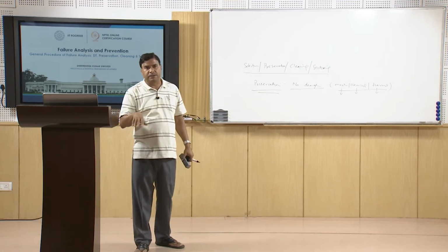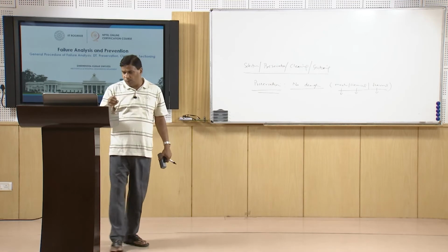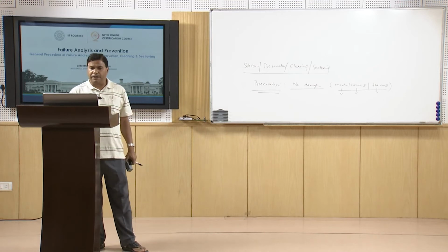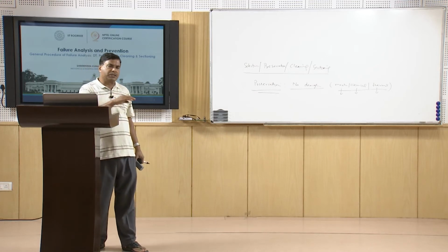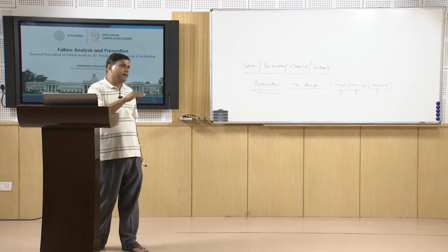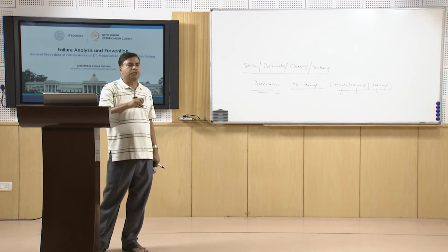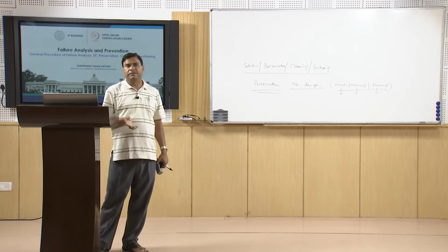So, that kind of precaution is also to be taken, that whatever foreign matter or particles are present on the fracture surface are retained, and we need not touch the sample, because it can leave fingerprints or things which were not there immediately after the fracture.